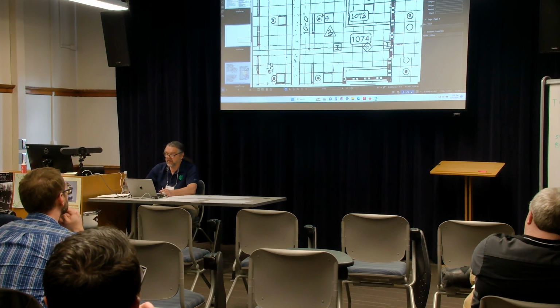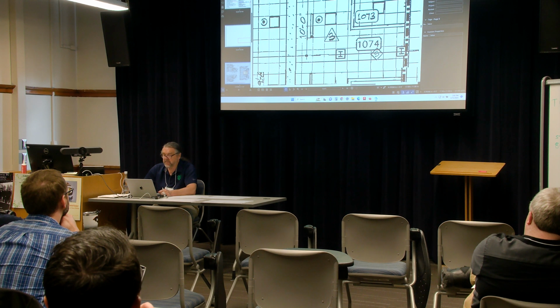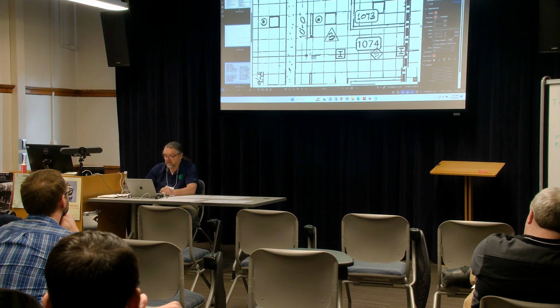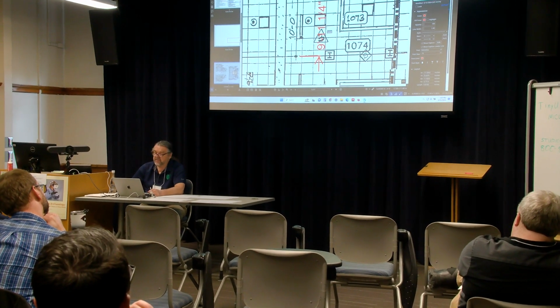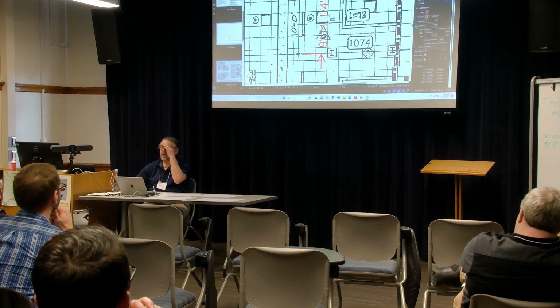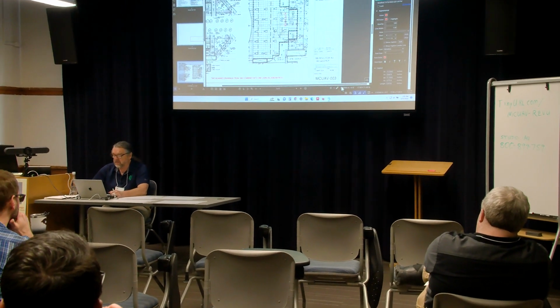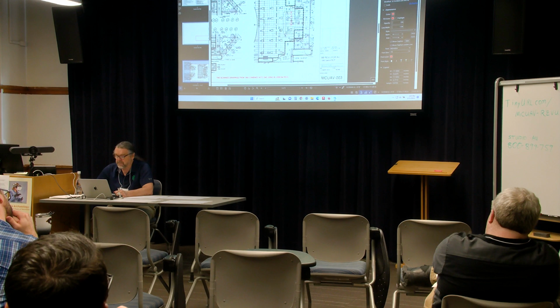Now I'm going to check my dimension. So the architect has shown that this is 10 foot. So I will grab the dimension tool and make a line and that shows 9 feet, 11 1/4 inches. That's good enough. That's going to tell me what I need to know. So now this drawing is scaled, and it's scaled in something weird, but that's okay.